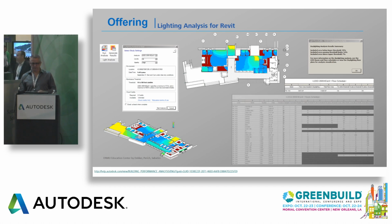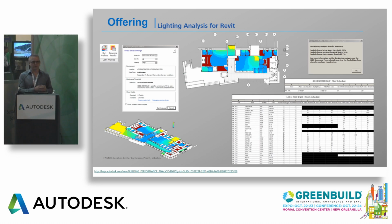And then the final piece of results is the full room by room performance for each threshold required for the LEED submission spreadsheet. Currently we do that for the 8.1 credit for version 3 of LEED and version 4 option 2, which is the point in time analysis. We currently don't do daylight autonomy.